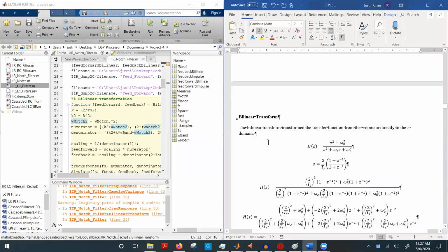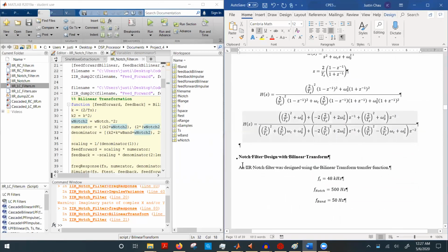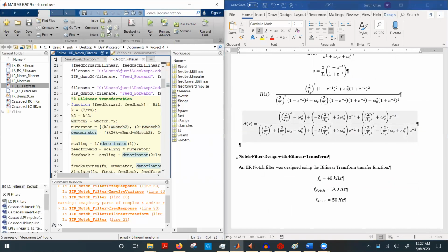One of the limitations of the bilinear transformation method is that it loses its linearity as you approach the sampling frequency's Nyquist frequency. So the sampling frequency must be much larger than the frequencies that you want to work with in order to use the bilinear transformation. So with that, just by applying the algebra, I've acquired the transfer function using the bilinear transformation, which is a lot simpler than using the impulse invariance method. So going back into implementing these, what we did in theory now in MATLAB.